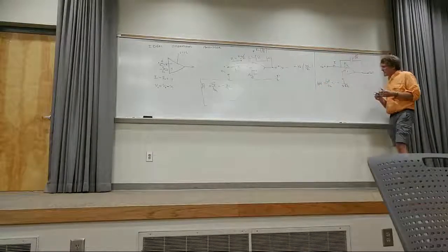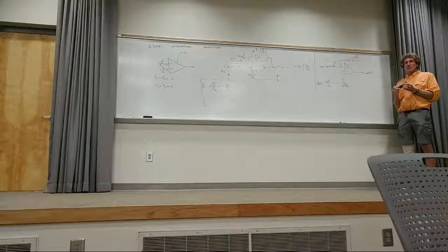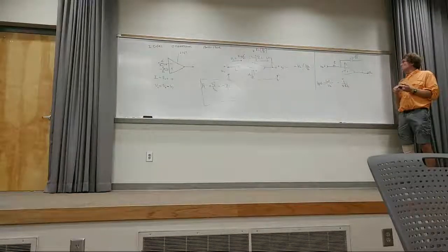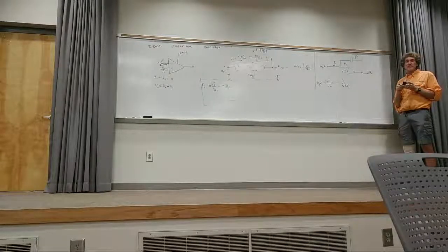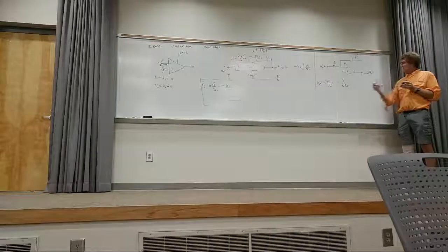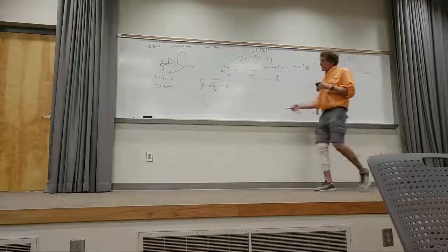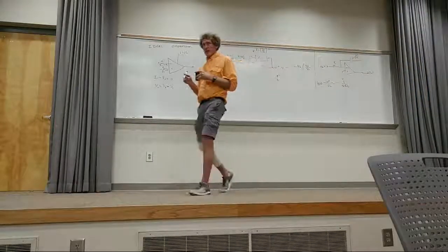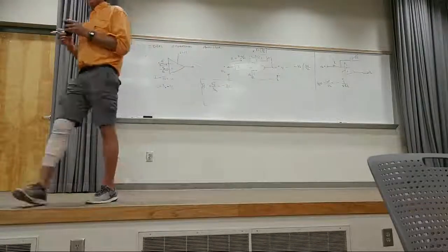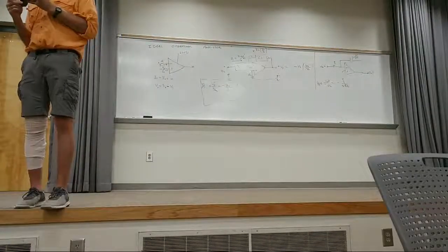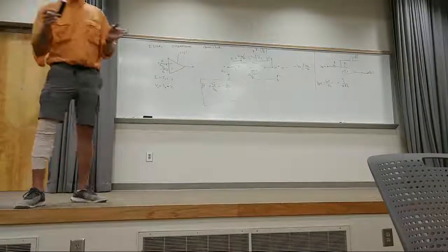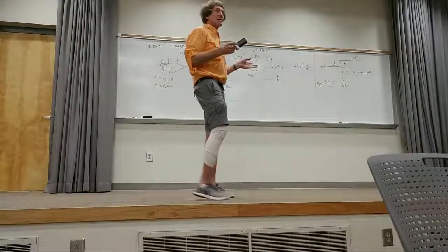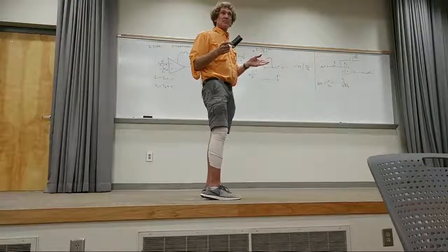Take a careful look at that. Do y'all agree with that? Output impedance, 1 over SC, divided by impedance R. It's 1 over RC with a minus sign, correct? Because it's got to have a minus sign, right? Please make sure you see that is equal to this. For that circuit where you have a resistor between the input and the negative terminal, and the positive terminal is grounded, and then you have a capacitor between the negative terminal and the output. All right, you all see that, class?